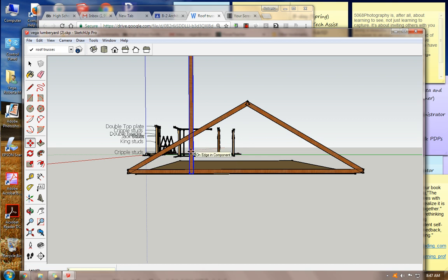Now I'm going to Control move a copy of this at 7 feet. And I'm going to move this now 7 feet the other direction, not Control move, just move 7 feet. And I have my 2 posts.